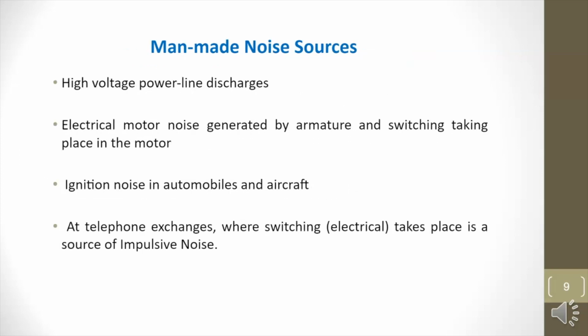The sources of man-made noise include high voltage power line discharges, electric motor noise generated by the armature and switching that takes place in the motor, ignition noise in automobiles and aircraft, and telephone exchanges where switching takes place as a source of impulsive noise.